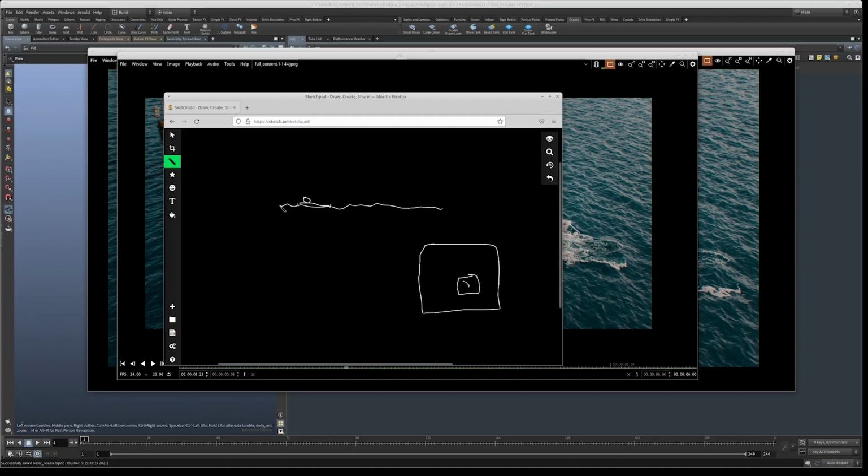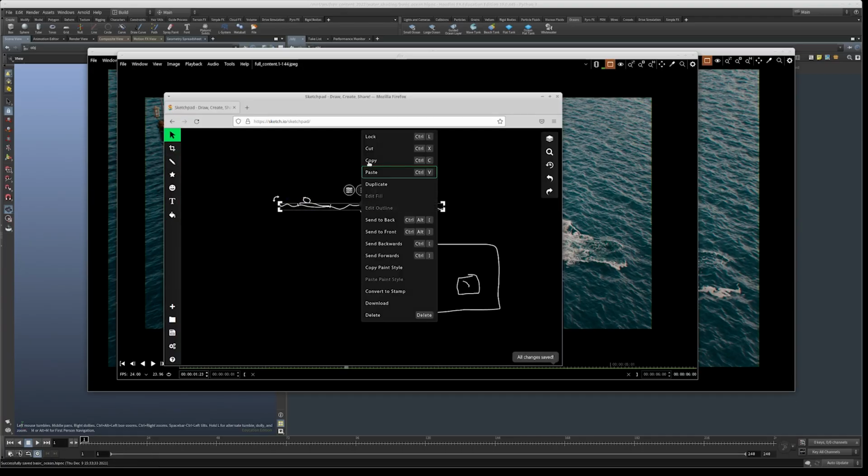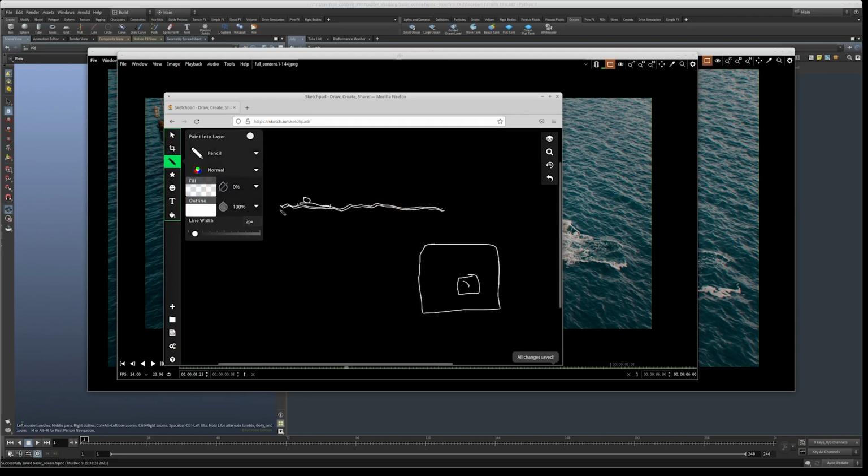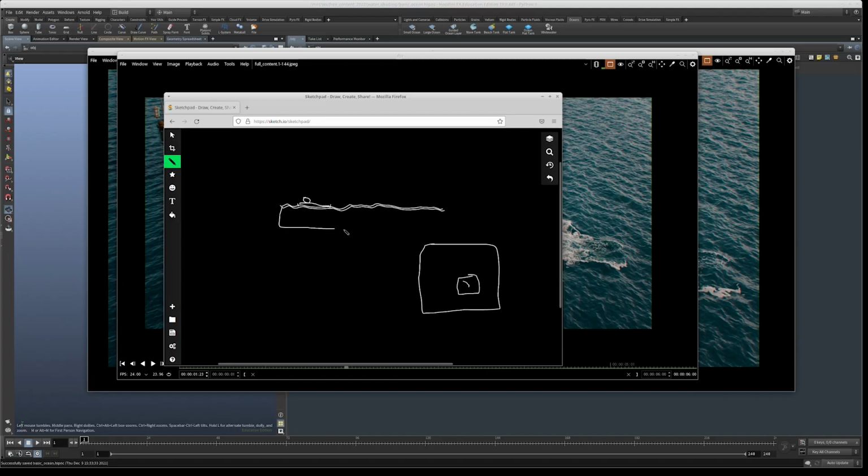But that's not all. So we end up with a surface, which is a geometry of the sim. And on top of that, we need to create something else. To get that nice volumetric look underneath the surface, we have to make a copy of this mesh. So I'm going to copy this. Let's say that's our mesh. What we need to do is make a copy of the same mesh and extrude it and give it thickness. Now this new mesh is just a box. It's just the same sim, but extruded, so it has thickness. This will be rendered as volume.